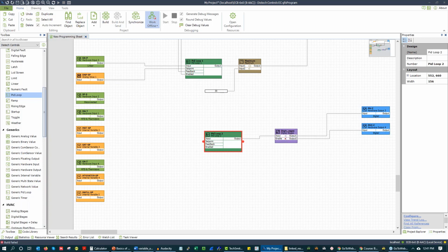And we would say, what? Mixed air temp is driving to set point to maintain its set point 5 degrees less than the supply air temperature set point. So first off, we grab mixed air temp, and that is going to be our input. And our set point is going to be mixed air temp minus 5 degrees less. So it'd be supply air. This is a convoluted way of writing this. Maintain its set point 5 degrees less. Okay, cool. I see what they're trying to do.